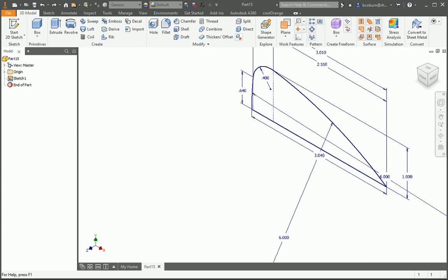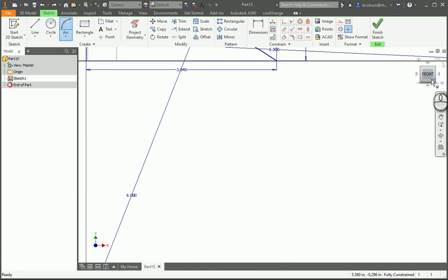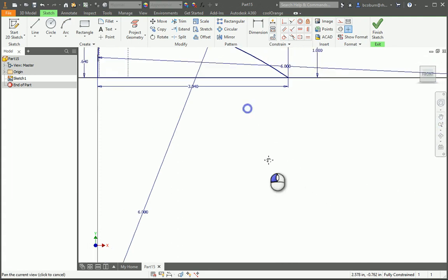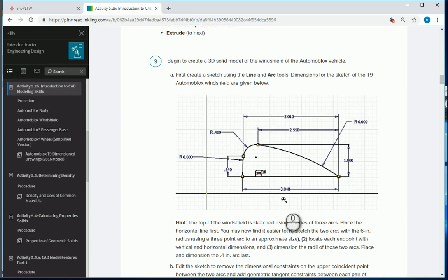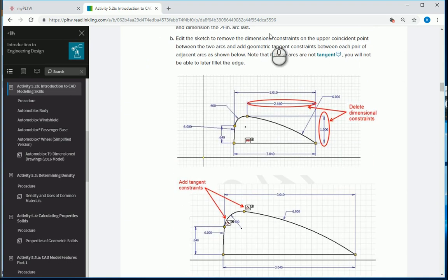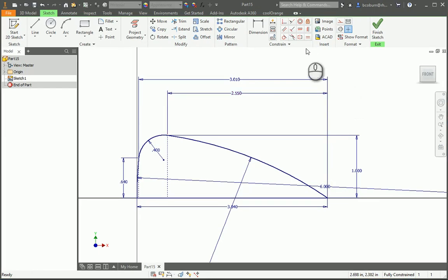And we'll go back to the curriculum, and there's 2 really important things we have to do with this sketch. And in order to do that, I want to take you back there and we'll look at it. As we scroll down, the part that the students will not pay attention to is deleting these 2 and then making them all tangent. I like making them all tangent. This one just says make those 2 tangent. But let's go back to the center and hit the tangent command.